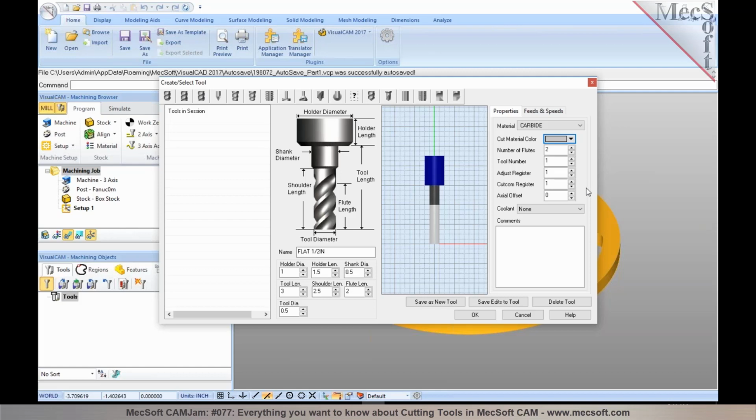And then if you're using cutter compensation, like a G41 to compensate left or G42 to compensate right, some controllers expect you to also output a cutter comp register, like a D followed by the register number. In most cases, you would also set this to be the same number as the tool number because it points to the table for the cut comp register, and the value that you're going to be compensating is what you would enter in the controller's tool table for the cut comp. So basically this maps to the tool table's registers. So you would want to specify these.